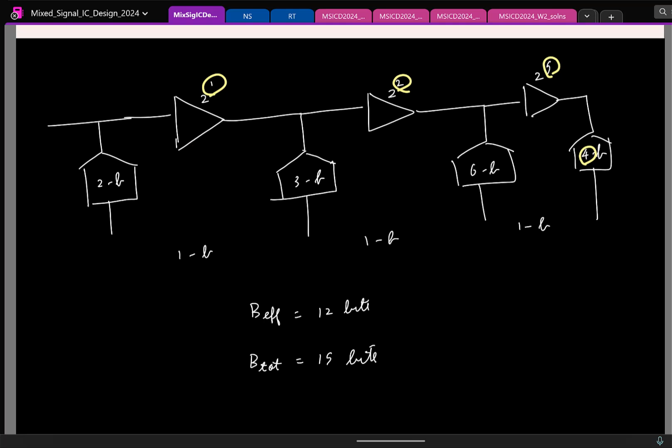So the idea is, if I use, let us say, a gain of maximum gain by 2, I can make some error in the comparator threshold voltages. So what we'll do is use the minimum number of comparators in each flash ADC, so that even if there is an error, gain times the quantization noise is within the range.